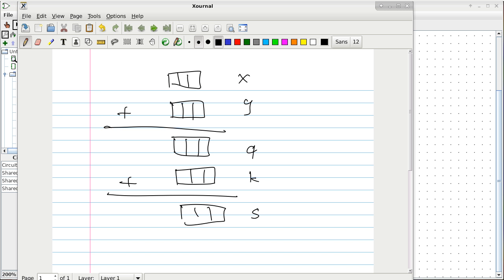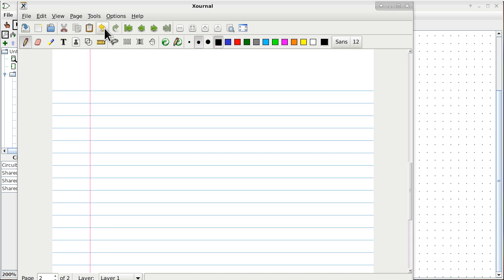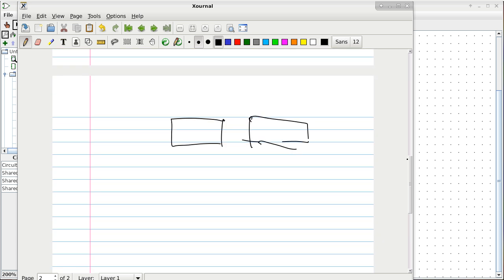So you can chain things, okay? Let me show you what I mean by that. Let's say you have a 3-bit adder here, and you want to add, let's say, 6 bits. But you're limited in terms of hardware, so you can only implement 3-bit adders. So what you can do is have another 3-bit adder, where K3 out of this circuit goes into K0 of the next circuit.